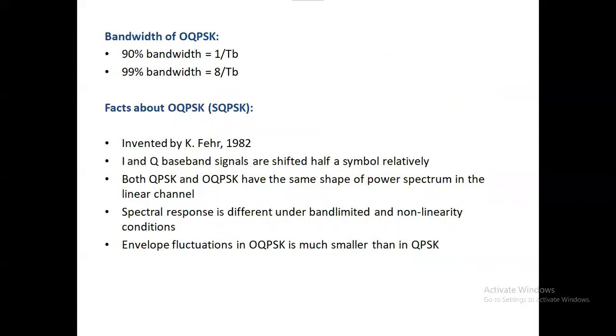The 90% bandwidth of OQPSK is 1 by T_B. So that is, in fact, sufficient for communication, and the bandwidth requirements are very good.